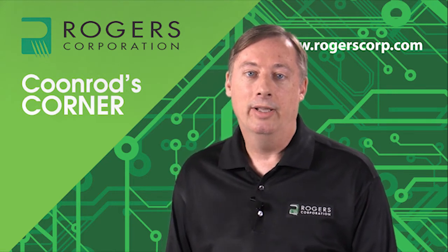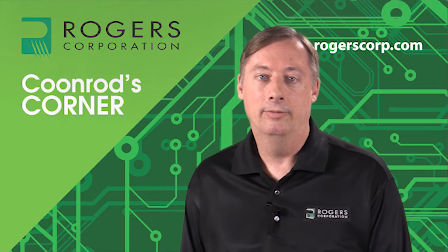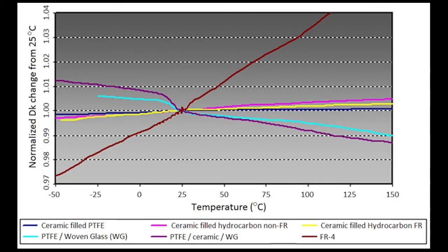So let's go ahead and take a look at some TCDk curves of different materials and make some comparisons. Shown here are several different TCDk curves for different materials. To begin with, the brown curve is a sanity check, and that's really FR4. FR4 is a material that's not considered good for TCDk, and I wanted to give you a reference for what a poor TCDk looks like, and that's really this brown curve. Now the other curves on here are all good TCDks, and a couple of them extremely good.